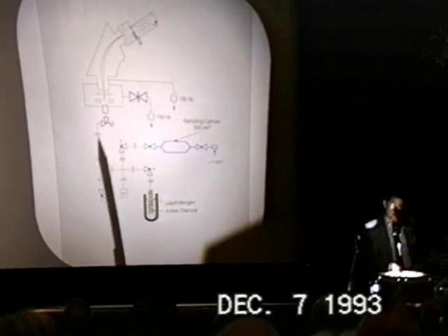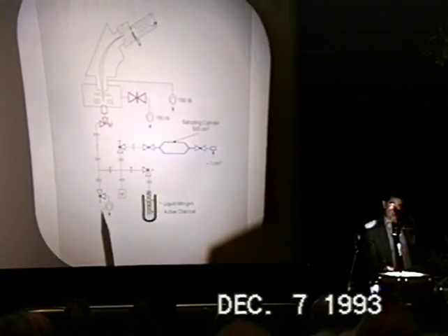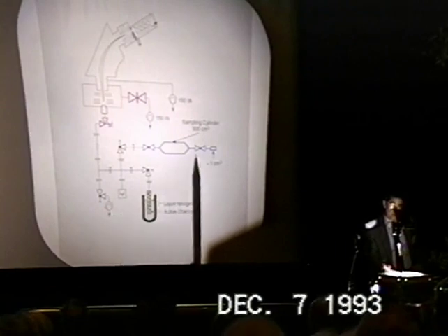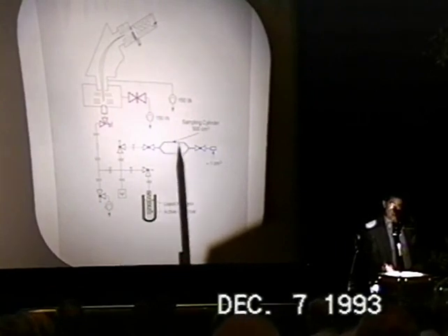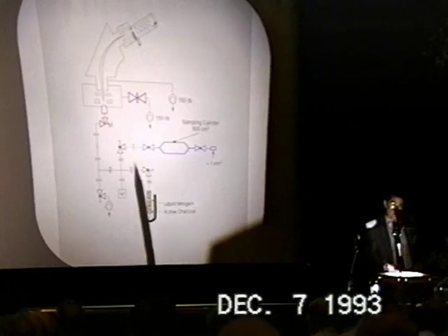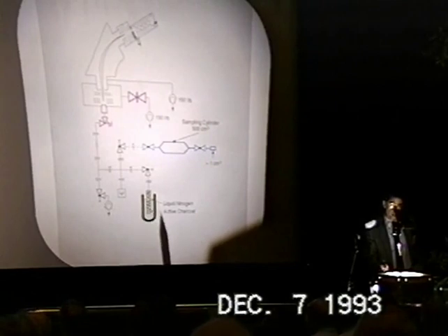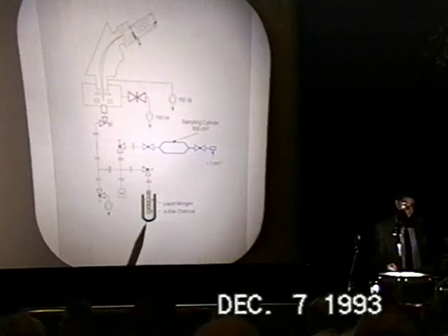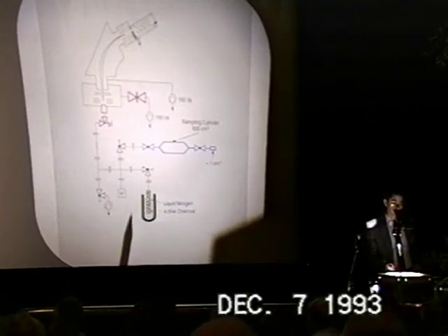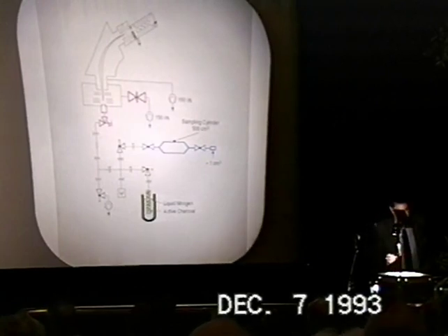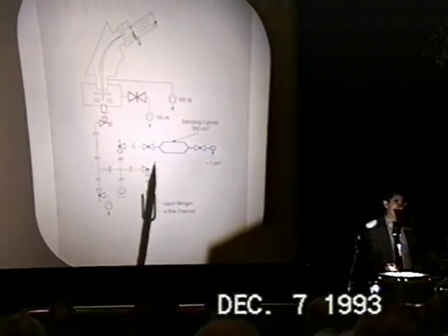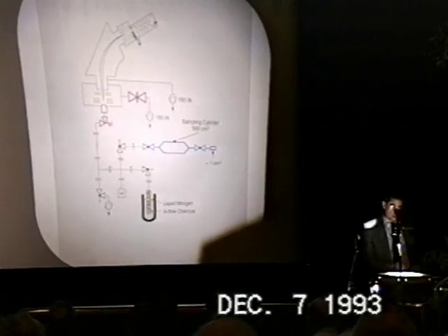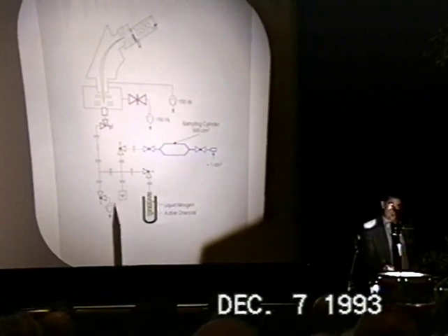And this inlet line can be pumped with an auxiliary diffusion pump so that the gas sample is allowed to expand into this inlet line and to be absorbed by the active charcoal in liquid nitrogen. Actually, what we are concerned with in this absorption stage is not the deuterium, because the collecting line already has a lot of capability to lower the deuterium content.